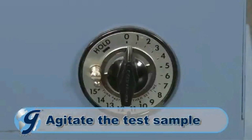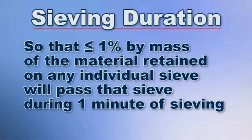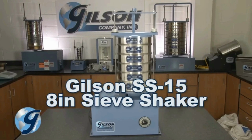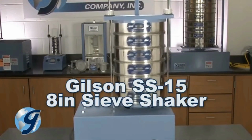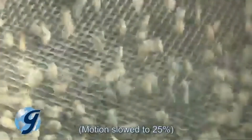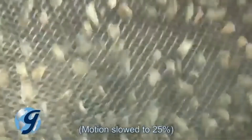Agitate the sieves by means of a mechanical sieving apparatus for a sufficient period of time so that not more than 1% by mass of the material retained on any individual sieve will pass that sieve during 1 minute of continuous sieving. For this demonstration, we are using the Gilson SS15 mechanical sieve shaker. The SS15 delivers superior accuracy and repeatability for particle separations by combining a back and forth lateral motion with an up and down and tilting motion, which causes test material to travel in an orbital direction on the sieve surface.